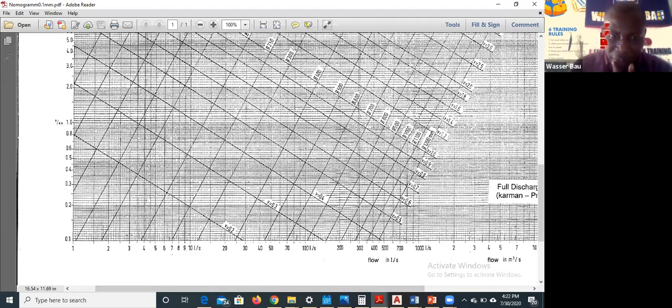This is 3, that's the biggest pipe, the main. I'm using a slope of 0.1, which in my own charts I'm going to use as 1. So I'll read 3, and I'll get it somewhere in between. Look at where it falls. That means it's between these two diameters: this one is diameter 100 and this one is diameter 125. So I'll use the bigger one, which is 125.